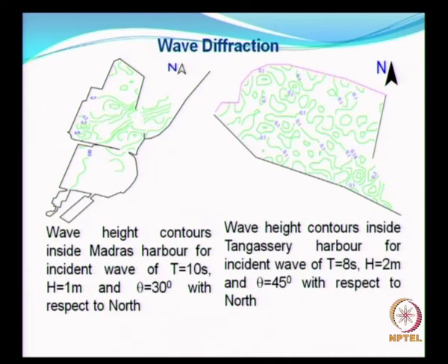Most of our breakwaters are permeable. Which is advantageous? Permeable is advantageous, because it will account for a certain amount of dissipation of incident wave energy. So we get a lot of information from this, and if you want to do some alterations within the existing harbor, then you can always feed it into your numerical model and try to understand what is going to happen if you change some of the items inside the harbor.